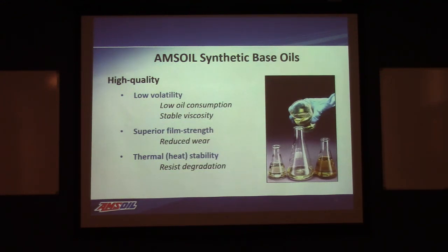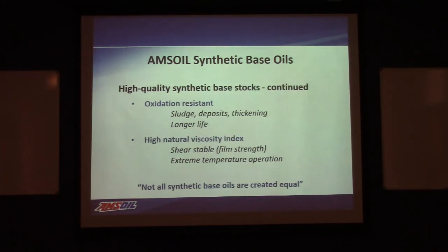We use stocks that are thermally stable, so they're going to resist high temperature degradation significantly better than the competition. Again, oxidation resistant. If these can withstand higher temperatures, there's less sludge and deposit formation, less oil thickening, and certainly it's going to extend the service life of the oil itself.